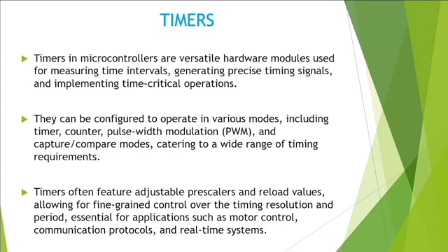They can be configured to operate in various modes including timer, counter, pulse width modulation and capture or compare mode, catering to a wide range of timing requirements. It controls the timing resolution and period, essential for applications such as motor control, communication protocols and real-time systems.